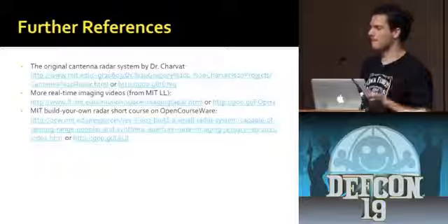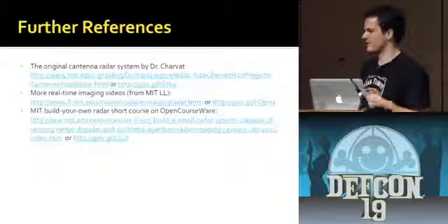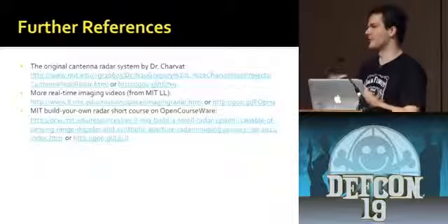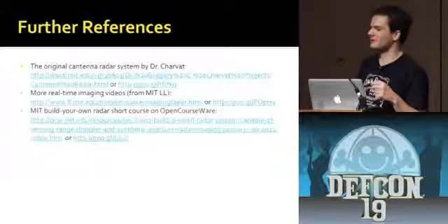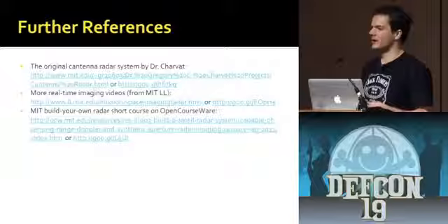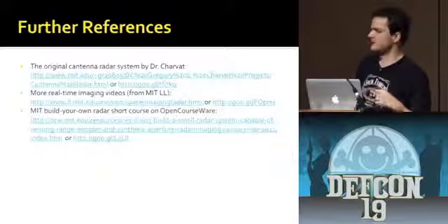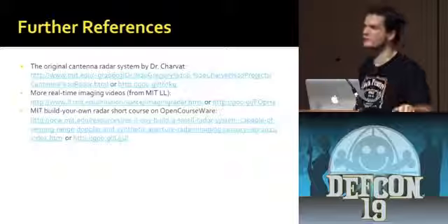So you could go up to 5 gigahertz. It would be a little harder to find parts. Basically, as you go up in frequency, the parts just get a little more expensive, and as you get even higher, they can get a lot more expensive. But the big thing you want in a system like this is wide bandwidth, because the bandwidth is what's giving you that spatial resolution and the time resolution.